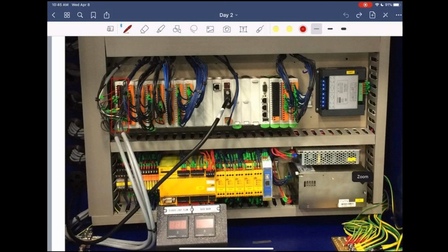Yes, this light will flash if it's good. There's a light in there. It's a red light, and it may look like it's in an error, but it's not. It's supposed to flash. These two gauges down here are for the amplifier card to calibrate the amplifier card for the back pressure.